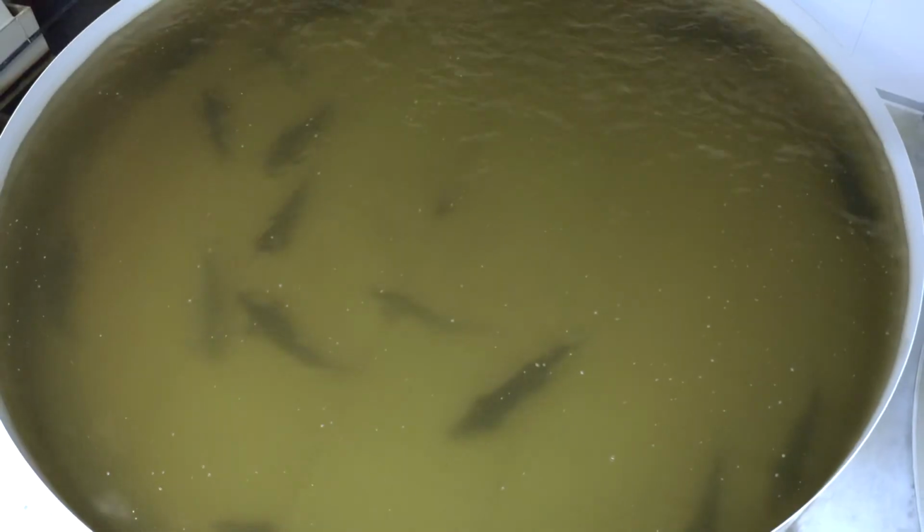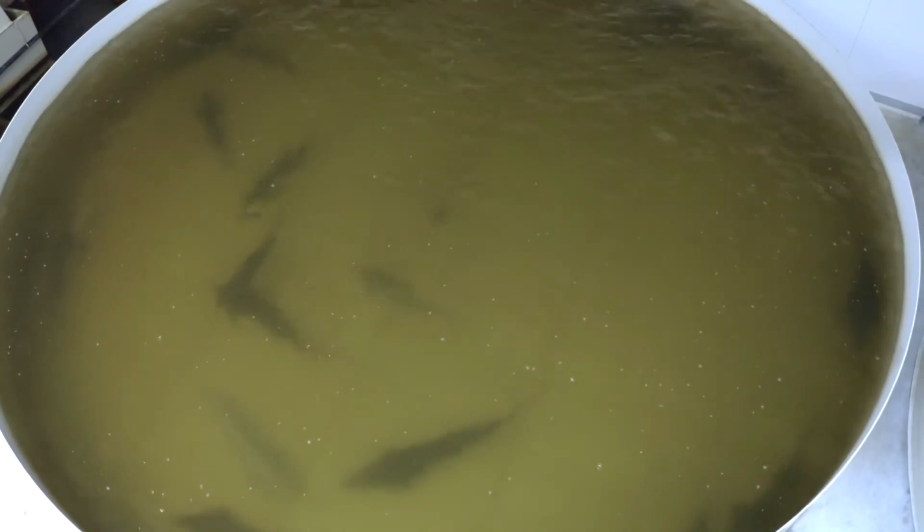Why shouldn't they be more than 8 meters in diameter? The answer is because in the case of a larger diameter, violating the diameter-depth ratio, the hydraulics, the movement of water inside the tanks, is disturbed. So dirt and suspended solids are no longer effectively removed from the tank. It starts to stagnate at the bottom and the whole process is disrupted. Of course, it's not very critical, but you will have to constantly clean these tanks. So it's recommended to make tanks for sturgeons no larger than 8 meters in diameter.